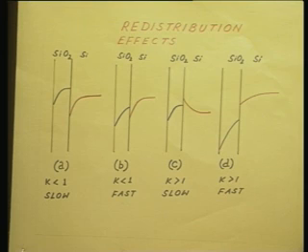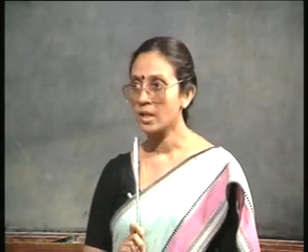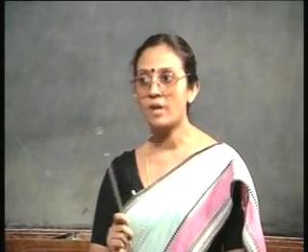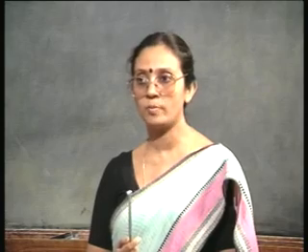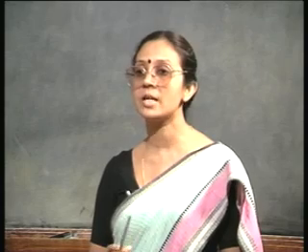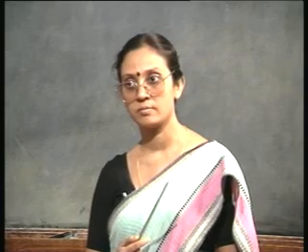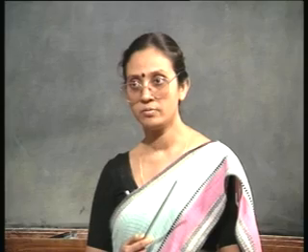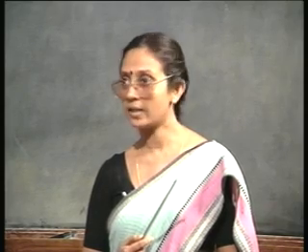So long as the oxidation process is governed by the reaction rate, you can expect a thicker oxide growth. That is why you see that when the silicon wafer is heavily phosphorus doped, the thicker or the faster oxide growth phenomena occurs at relatively lower temperature, where the reaction rate is dominating the process. Okay? Agreed?